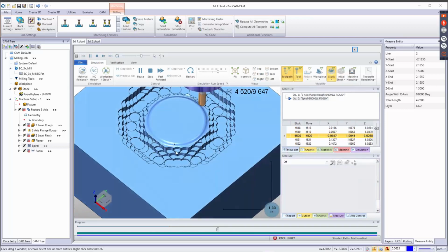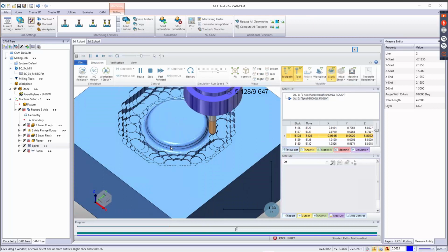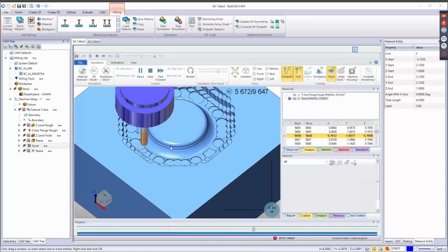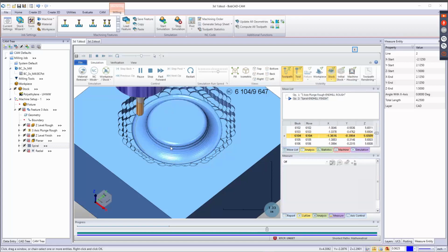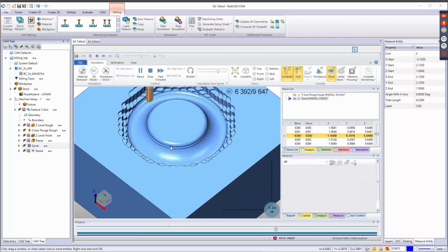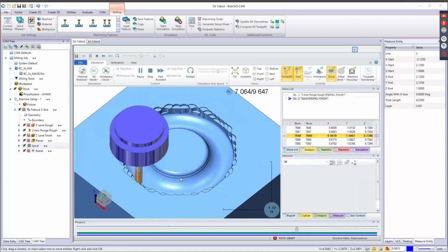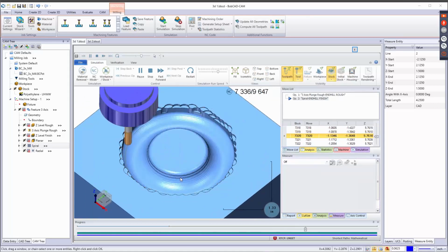So far it looks like a toolpath I could possibly use on this. Again, I might have to adjust my inside diameter and my step over amount on there. But it keeps the tool engaged the whole time. Really nice there. Right mouse click allows you to pan right, left, up, and down. So that's what I just did there.